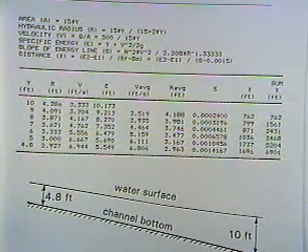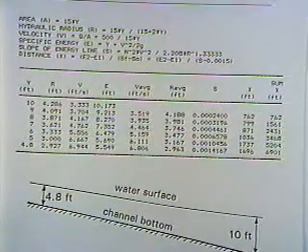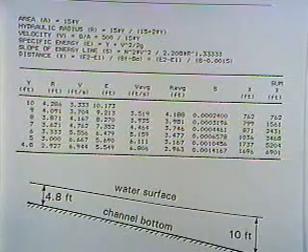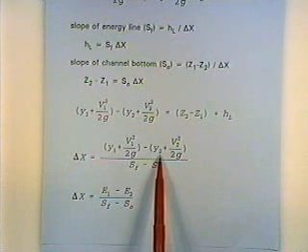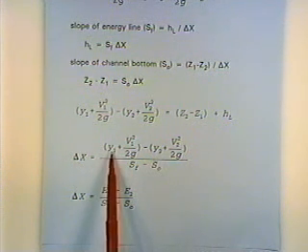What we'll actually compute is the location, the delta x. If we go back to our basic equation, we'll be plugging into that equation over and over again. I'm going to flip back to it a few notes back. The direct step method for gradually varied water surface profiles, we're computing the delta x. At some place the depth is 10 feet. We'll plug in 10 feet here, 9 feet there.